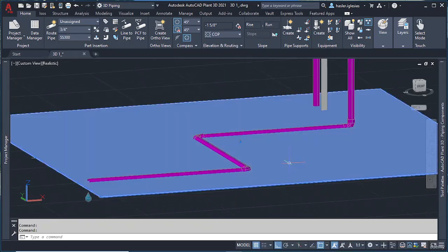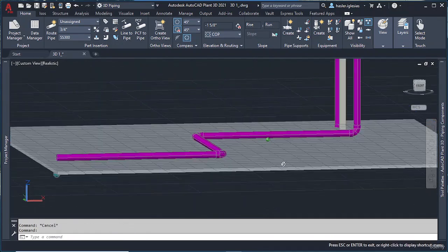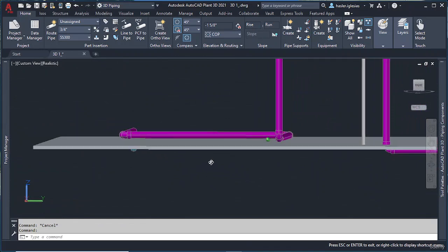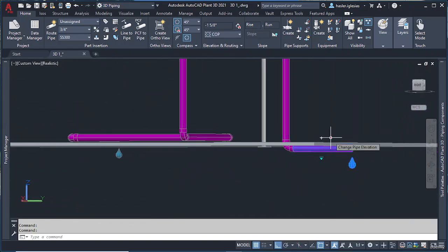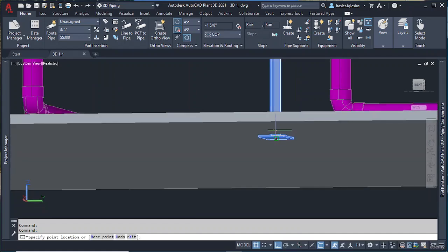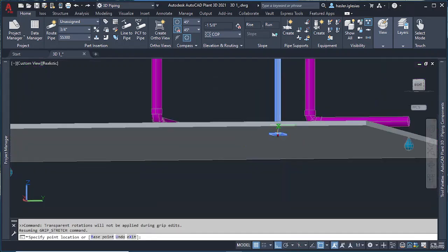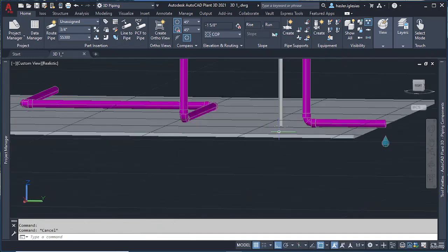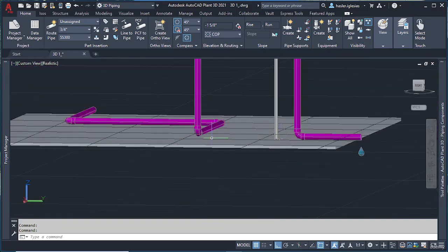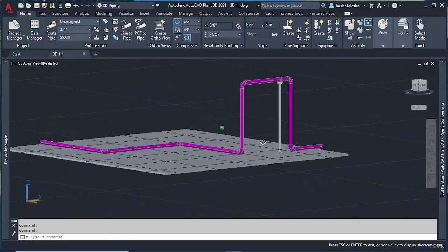And now I would like to move it down so it doesn't intersect the piping. So now here I'm okay. Here this piping is below, so I can move it, right? I can put it there, for example, and I can also move this by clicking just here on this arrow, which allows me to change the elevation. Sometimes it's tricky, and it will take a lot of time for all of us to get used to this 3D workspace, because the visibility is not always the same as the coordinates we're working at. So now we have the floor.